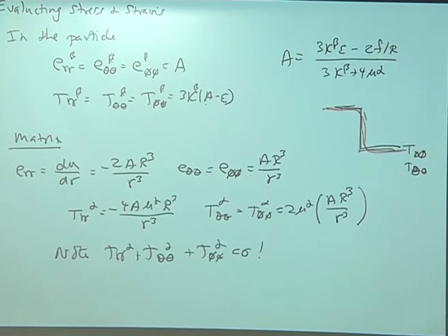And then you can ask all the questions we asked: is this sharp interface model, the black, and the diffuse interface model, the red, that you get from the phase field model, going to give you the right stresses at the interface when you have this jump? That's why this is an important sanity check on your phase field code.